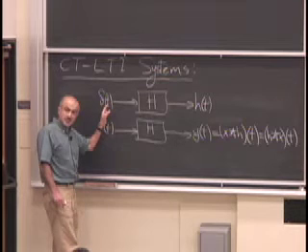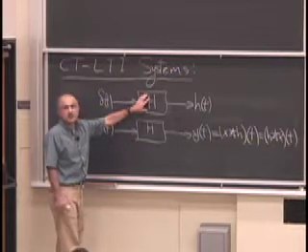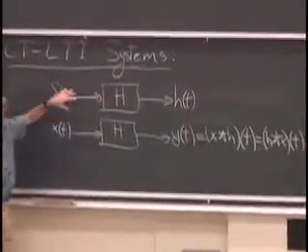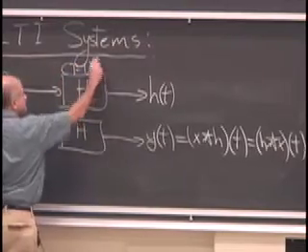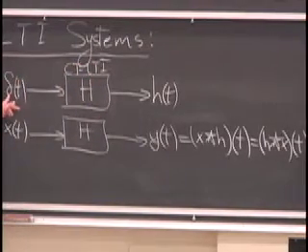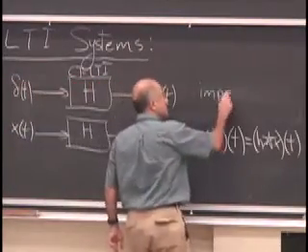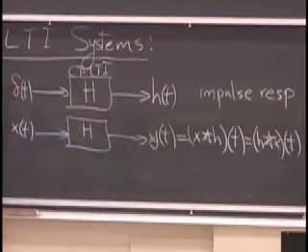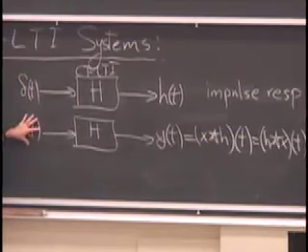One property of discrete time LTI systems that you came to understand was that they are completely characterized by their response to an impulse. And the same story holds in continuous time. If you have a continuous time LTI system, and you give that system an impulse input, you get some kind of a response that we call the impulse response of the system. And it turns out that that impulse response characterizes pretty much what the output will be if you change the input to some arbitrary signal, x.